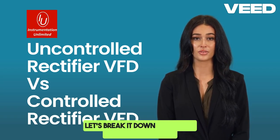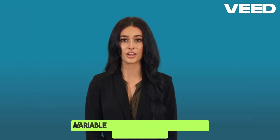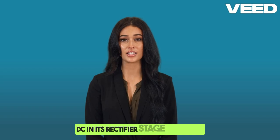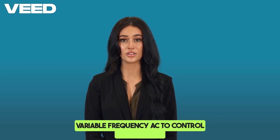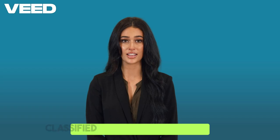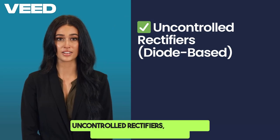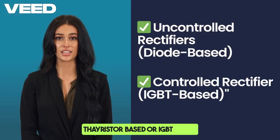Let's break it down. Before we compare them, let's quickly understand what a rectifier does in a VFD. A variable frequency drive, VFD, converts AC power into DC in its rectifier stage and feeds it into an inverter to convert it back into variable frequency AC to control motor speed. The rectifier plays a crucial role in determining how well the VFD manages power and controls the motor. Based on its design, rectifiers can be classified into two types VFDs use: uncontrolled rectifiers, diode-based, and controlled rectifiers, thyristor-based or IGBT-based.